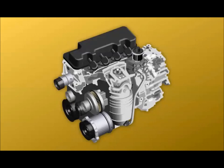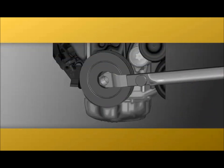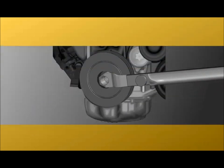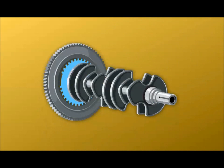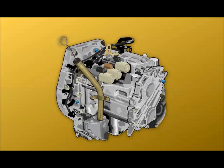If this eliminates the binding, check all accessories for binding. If the binding remains with the accessories disconnected, remove the timing belt or timing chain and check for binding again. If the binding goes away with the camshafts disengaged, check for binding in the camshafts and cam drive system. If binding still remains with the crankshaft disconnected from the camshafts, the problem is most likely in the crankshaft bearings, but also check for binding in the transmission pump or input shaft.